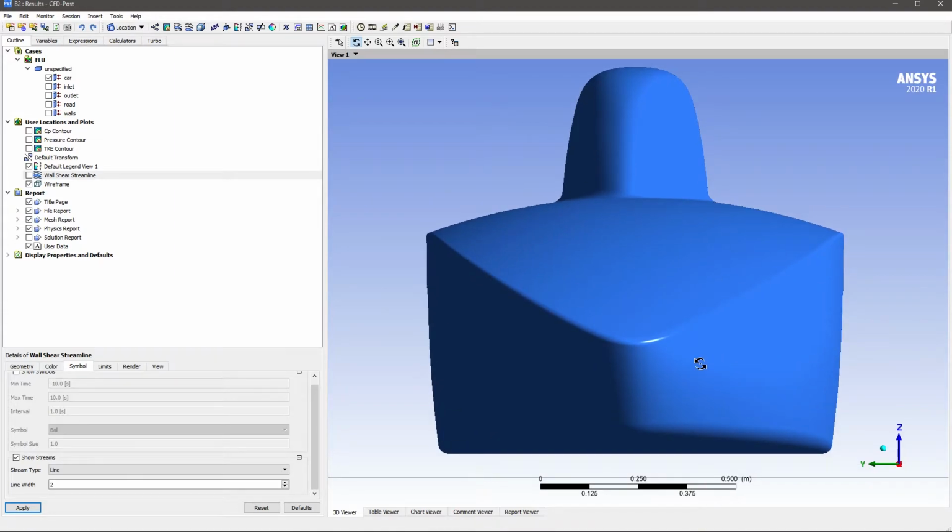If you notice that the car is cut off or too big or too small on the viewing plane in your pictures, so you would check your pictures to review how all of them look afterwards. I'd make sure you double check your work. And if you notice that any of this is happening, then you can simply adjust the view. So if the car is too big, then zoom out. If it's too small, then zoom in. And if it's cut off, then you can pan around, which you would do by clicking Control and the middle mouse button. You can see the mouse turns into a translation icon as opposed to a rotation icon.